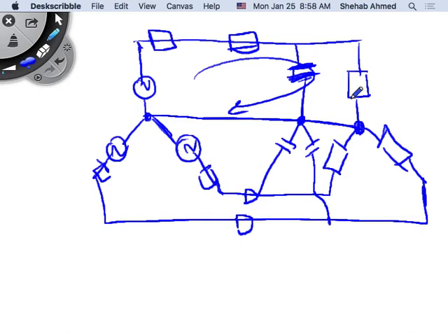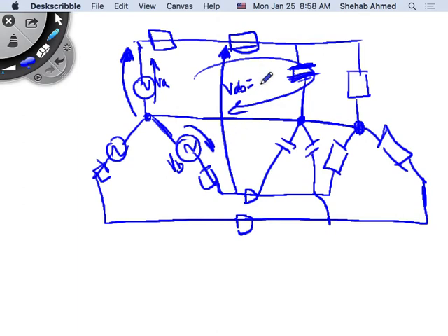But you have to be careful that the voltage provided here is called what? This is the phase voltage provided by my source, right? Is this voltage equal to this voltage? It's not. If this is VA, this is VB, what is this voltage? VAB is equal to VA minus VB, right? So this is called the line voltage in this case, and this is called the phase voltage. So there's a difference in magnitude, and then there's a difference in phase shift. We will look at it on the slide as well.